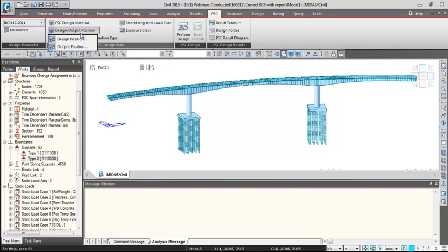Design obviously we need to perform so that we could check what's happening at different locations, but if you give output at all the locations, then to generate the Excel report the software will give you the Excel report for all the 149 elements at the I and J location. So that would be 298 sheets, plus there will be result table sheets and all. Generating an Excel workbook with so many sheets will take a very long time. Moreover, most systems won't even have the capacity to open an Excel workbook with so many sheets, right? So to restrict that, we select certain critical sections for output.